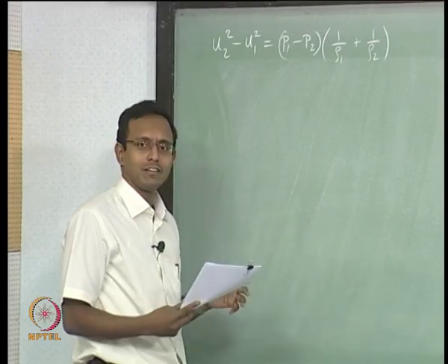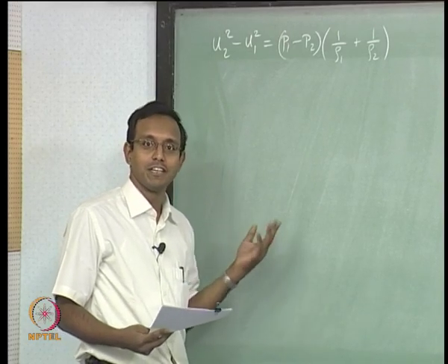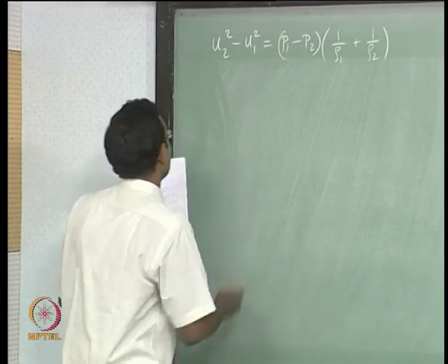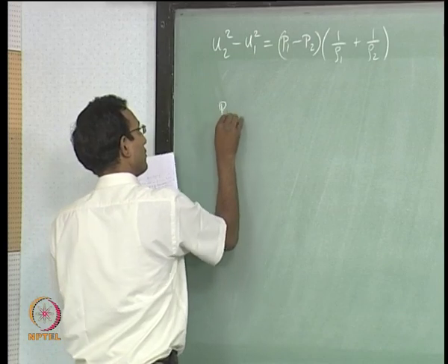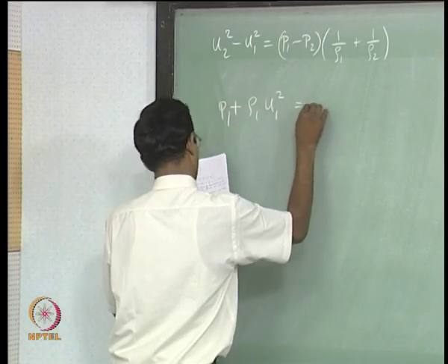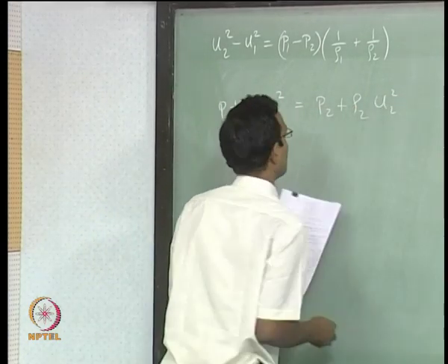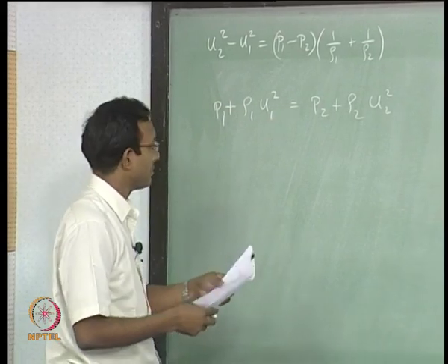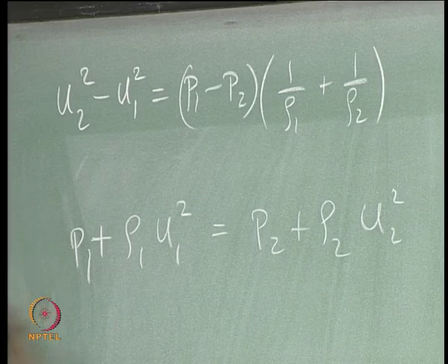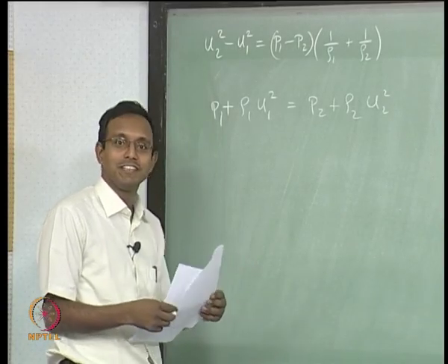Now we want to eliminate all variables, pressure, temperature, density, velocity, everything in terms of Mach number. That is our ultimate goal, of which we started here. We had this relation, constant area momentum equation, a special case, but it is valid for us because we are thinking across a shock which will be a very thin layer anyway.